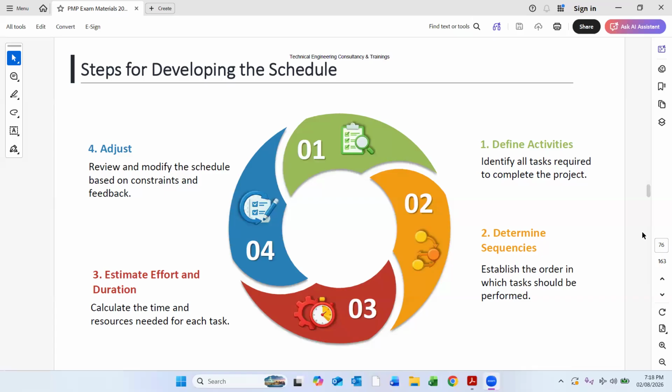Again, in the productivity calculation we have resources. We need to assign the resources, manpower and equipment. Then we need to add some KPIs as part of our calculation, and put in some formulas where we can get the progress values. For cost, we need to do the cost loading as per the BOQ. So this is how we develop the schedule.